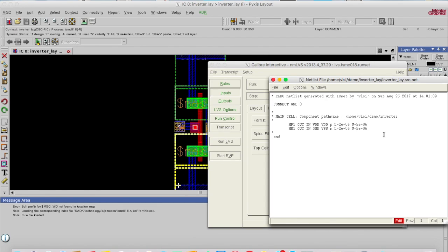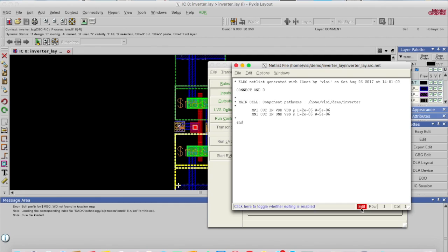So now I can view, yeah, it is showing this, but this netlist should be compatible with the netlist of layout, and in the layout netlist we generally have a subcircuit definition, so we should include that circuit definition here, and we should follow the same format. So I'll do the required addition. So go and edit. So I'll add the subcircuit definition.